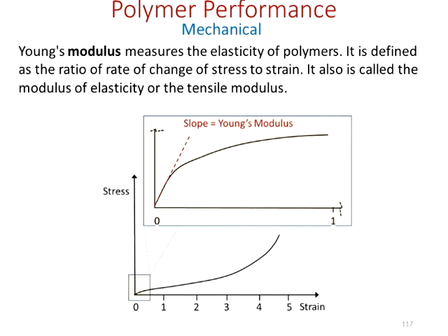We have to pick a point where it makes sense to measure the slope. For Young's modulus, which is by far the industry standard, we measure it where there's very small movement in the stress strain curve. So you go back to the beginning of the stress strain curve, take a look at the slope at that point before it starts to deviate, and that's where you draw the line. And that's a very consistent process.